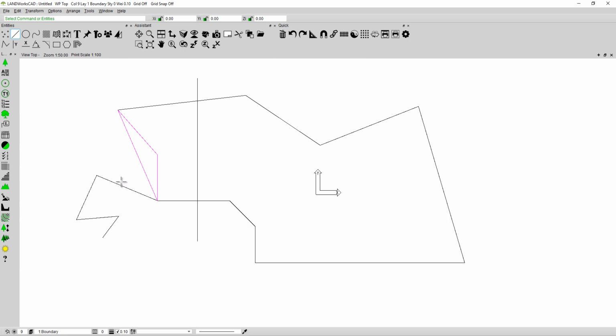It also allows me, if I hold either the Control key, the Command key on a Mac, or the Shift key on both a Mac and a PC, to add extra lines to my selection of lines. And by reselecting whilst still holding the Shift key, I can deselect various lines. But now that I have some lines selected, using the ability to just click on them with the diamond showing, I can now throw these lines away, or delete them, or move them, or do anything with them.